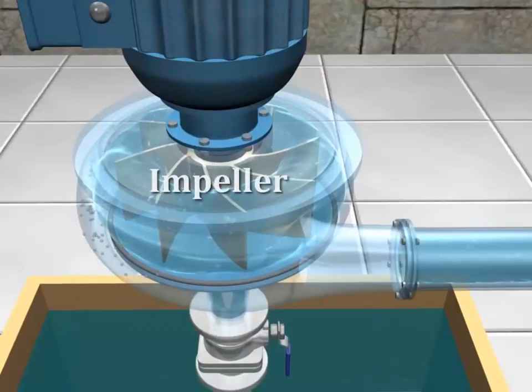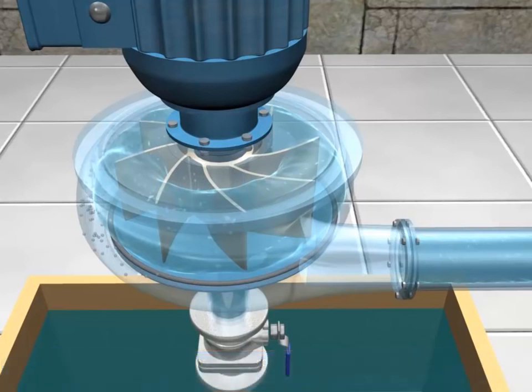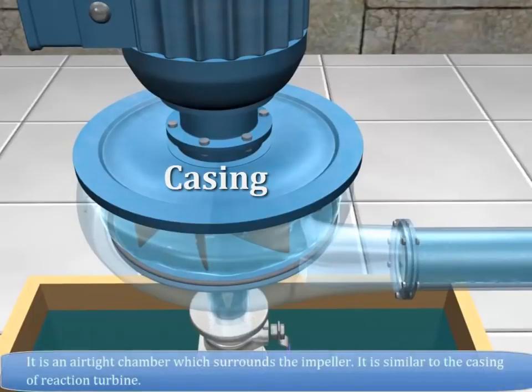Impeller. It is a wheel or rotor which is provided with a series of backward curved blades or vanes. It is mounted on the shaft, which is coupled to an external source of energy which imparts the required energy to the impeller, thereby making it rotate. Casing. It is an airtight chamber which surrounds the impeller. It is similar to the casing of a reaction turbine.